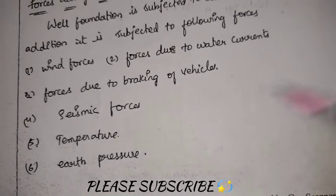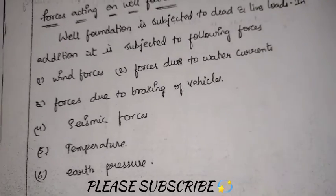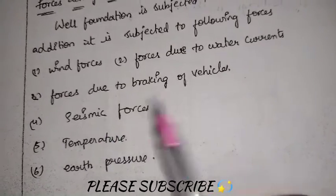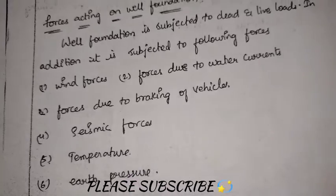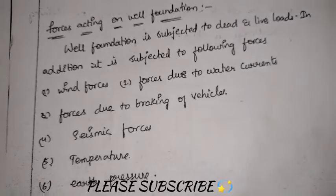Forces due to breaking of vehicles: whatever impact load occurs from sudden application of brakes on vehicles will cause this force. And seismic forces, that is earthquake forces, are unpredictable in nature. Temperature: due to the rise or drop in temperature. And earth pressure. So these are the general forces that act on the well foundation.